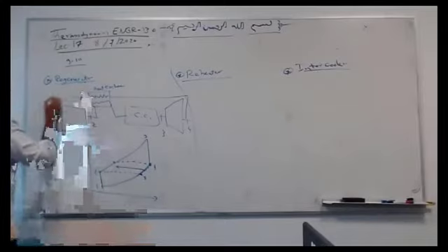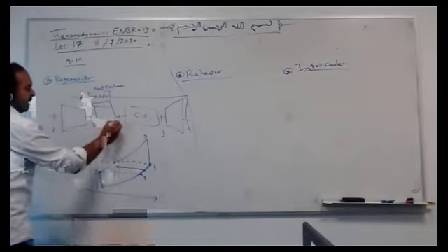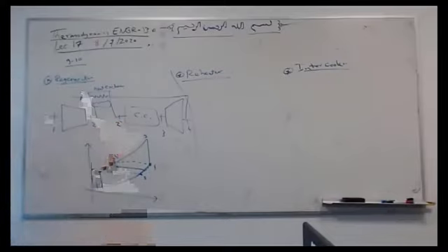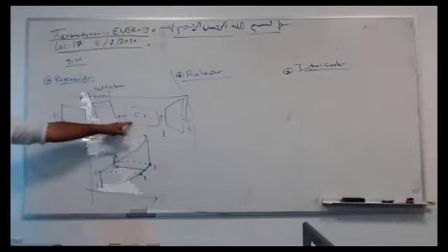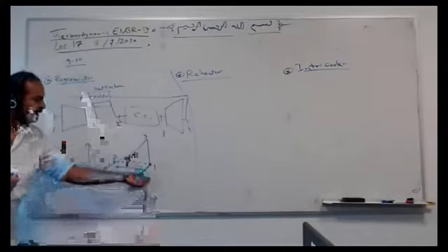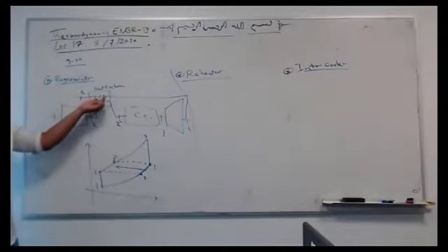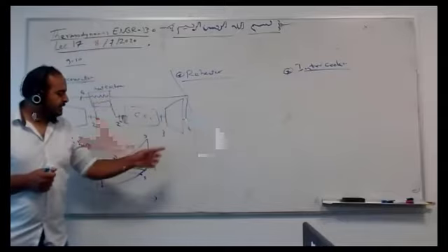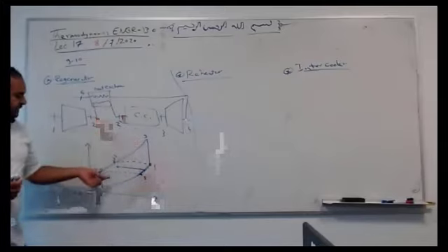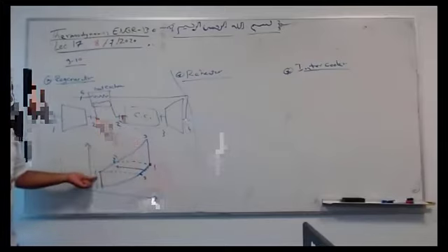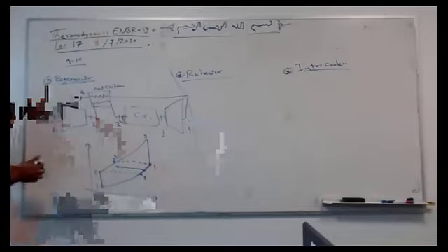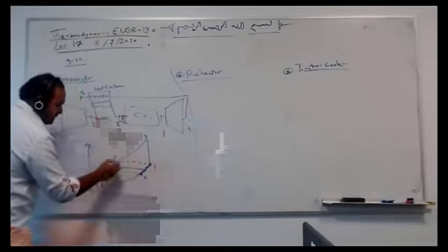4, and this is 5. And this is, for example, let's say 2 dash. So what happened? Instead of using the whole fuel here to burn from 2 to 3, no, I will take some heat from 4 to 5. This is already dumped in the air. This is a lot of heat, especially if you have a higher temperature difference. So T4 is much larger than T2. If that is the case, I can take some heat from here and give it to here. Exactly this difference.